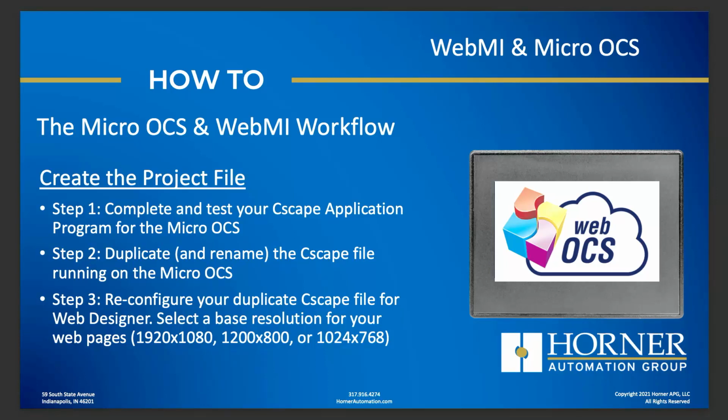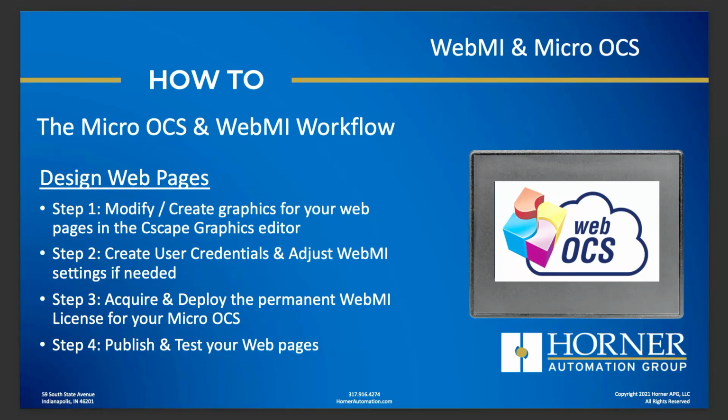Now don't worry, regardless of which resolution you choose, you're going to be able to see these pages on a tablet or on a phone or on a full computer, and they'll scale up and down just fine at runtime. You just need to pick a base resolution for the pages that you're developing in Cscape. Okay, so that's the first half of it. Do your normal project, duplicate your file, rename that file, and then change the configuration to be a Web Designer configuration.